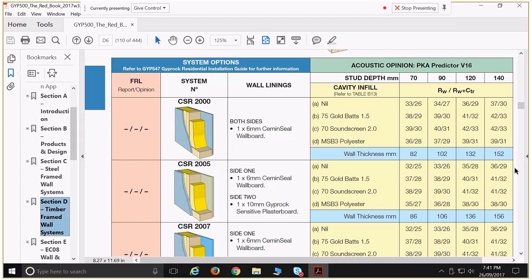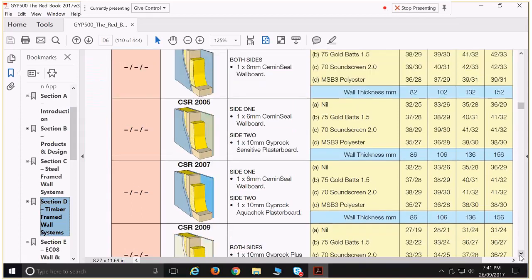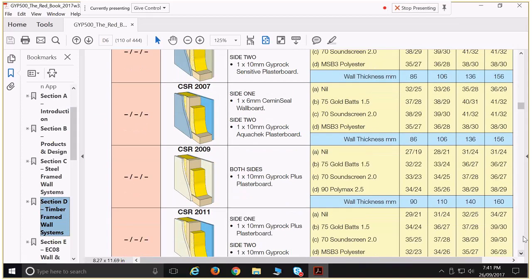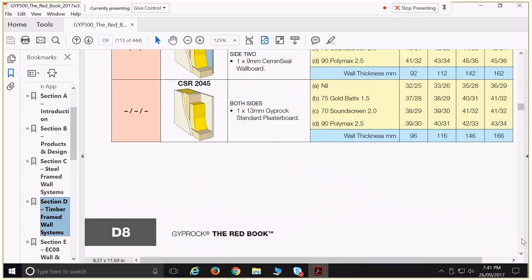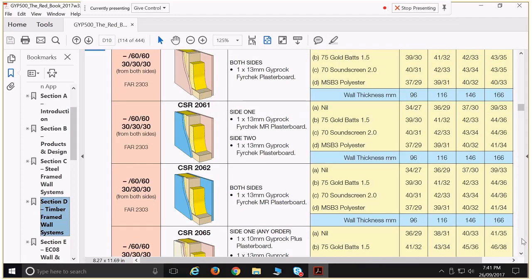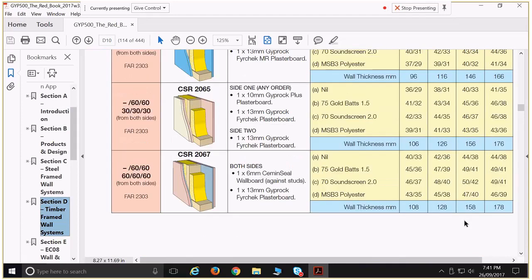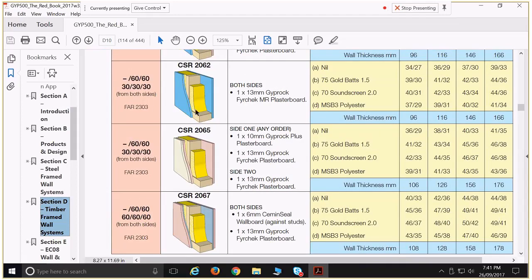It doesn't meet any fire rating levels. Scroll further down to where we start meeting fire rating levels. So with our timber systems, once again, our structural adequacy is the linchpin, so it will have 60 minutes of integrity, 60 minutes of insulation, but then it'll only have structural adequacy for 30 minutes, so those others will be compromised after 30 minutes as well.